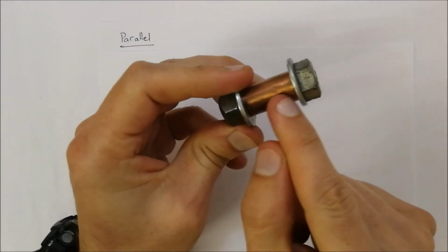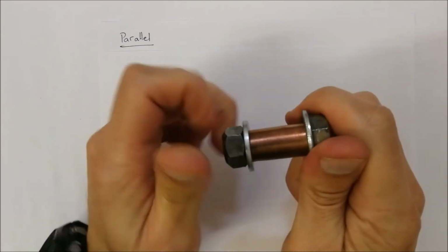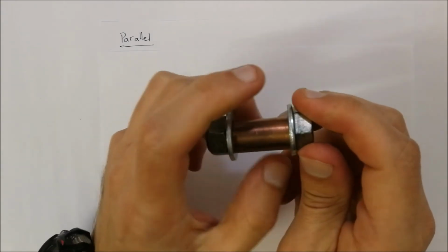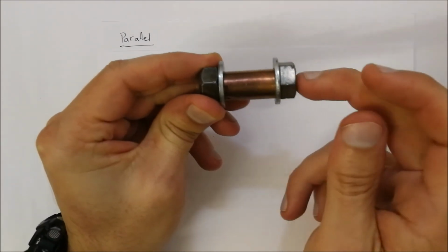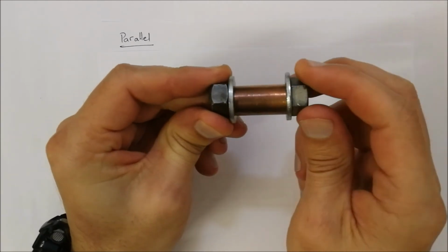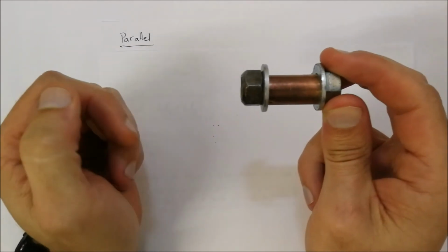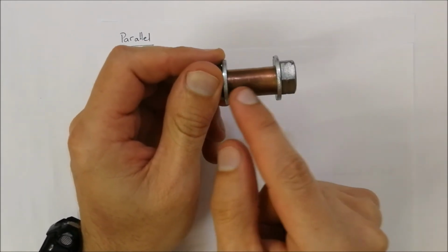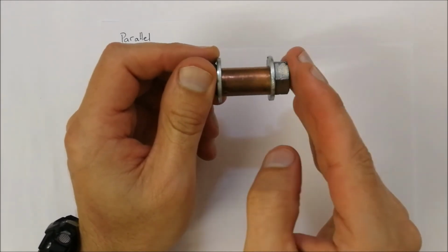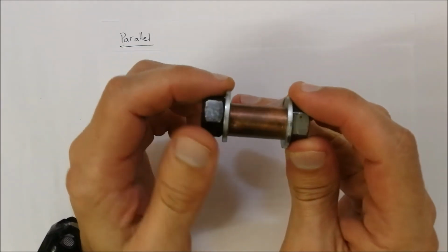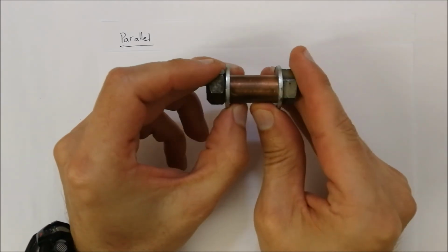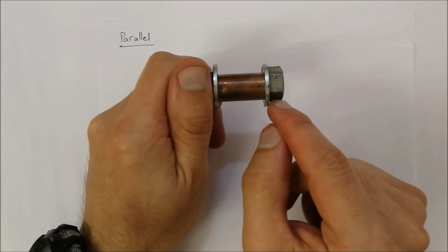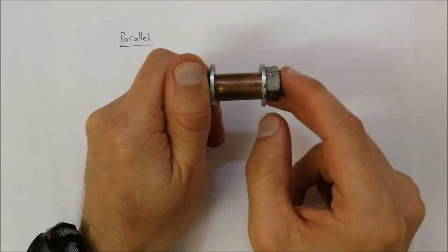Well, there's going to be compression on this copper tube because I'm tightening it. But as I'm tightening it, that also means that there's going to be some tensile forces acting on the bolt itself, because it's basically now pulling away from each other, while it's also causing this copper piece of material to have compression on it. So in this scenario, with the bolt being in the center, that will have some tensile forces acting on it, yet there will be compression forces on the copper material.